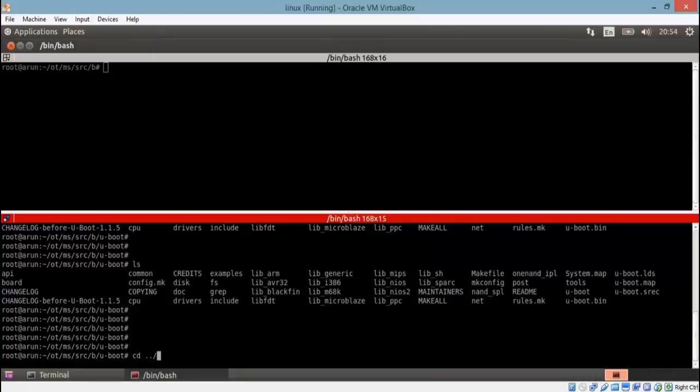Are you getting my point? Let's say there are some hardware guys designing a specific board with an ARM SoC for some specific purpose. The software guy has to write U-boot, the primary bootloader, to initialize the memory, the peripherals, the devices, the buses, and everything.